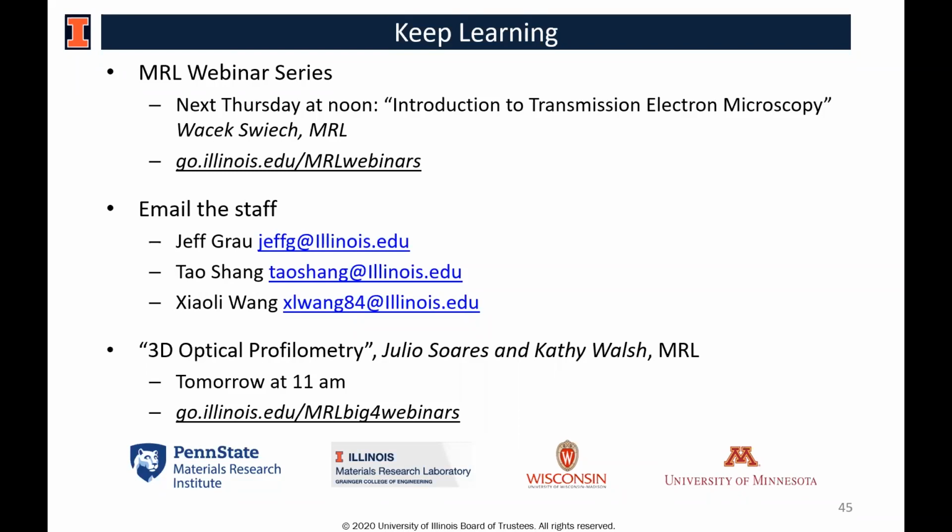Well, actually, the way we generate the photomasks has a lot to do with it. The MJB4 is a later generation of the aligner, so it does have the capability of going down to 1 micron. The MJB3s can also do 1 micron, but we typically favor those for anything above 3 microns because typically we were only able to achieve a 3 micron feature on our photomasks.